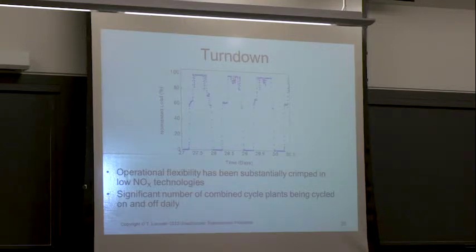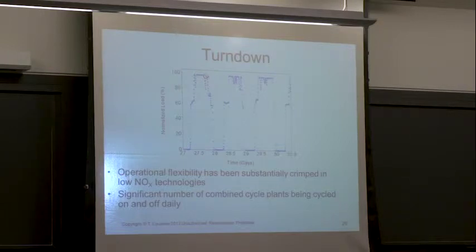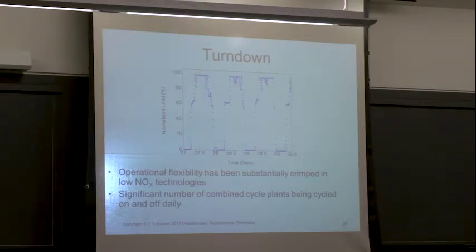So this is a huge power plant. I'll just tell you that the heat recovery steam generator on one of these power plants is the size of this building, all right? It's massive. This thing was designed to run 365 days a year, 3 years straight. Turn it on, run it for 3 years, shut it off, clean everything up, turn it back on after a couple weeks. They are actually taking this enormous power plant, turning it on in the morning, shutting it off at night. So massive thermal cycling.